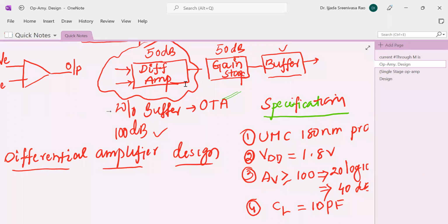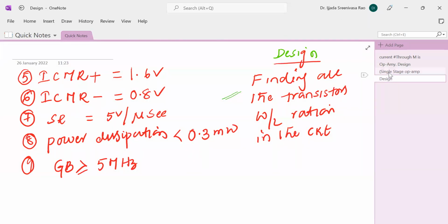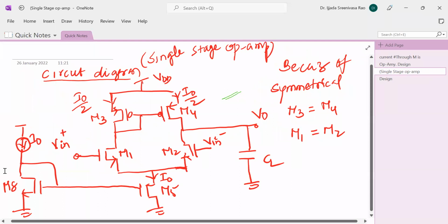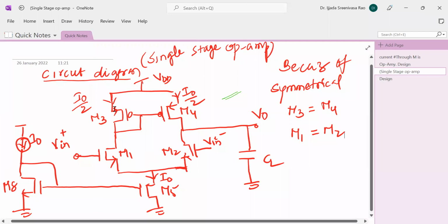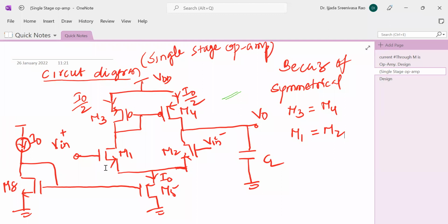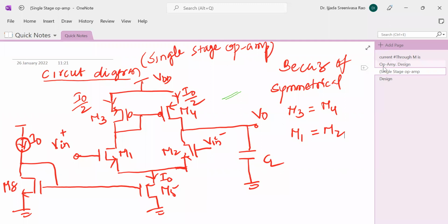So how to design the differential amplifier? Here is the differential amplifier circuit. Design of the differential amplifier means finding the W by L ratio of all the transistors in the circuit: M1, M2, M3, M4, M5, M8. All these transistors' W by L ratios should be found. So for the design of this single stage operational amplifier, we need the...